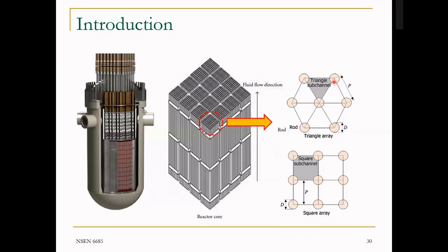Then the spacing here is called the pitch between the fuel rods. Could be here the pitch. Remember, this is a square lattice. So this is pitch. Horizontally, it's still P. The same for that equilateral triangle. So that's P. That's P as well, right? So these are the major assemblies. So now let's pick one of these fuel rods and look at the construction of it, how it looks like.